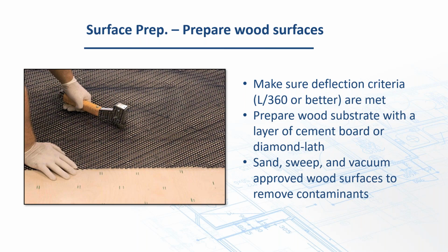Make sure your deflection criteria is there, that you don't have too much deflection. Make sure it is clean. The key to any leveler is cleanness. Make sure that you get a good bite to that surface. Remove any contaminants like overspray and things like that. Sand, sweep, vacuum, sometimes even lightly mop.